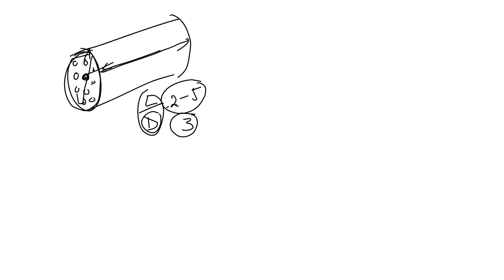And then I think you've done this in heat transfer design, where when you have tubes, you have a certain pitch. If I've got 100 tubes, I must arrange them in a certain pitch arrangement, square pitch or triangular pitch. Now I arrange 100 tubes, and this is what my bundle diameter will be. So this is the whole diameter of your reactor.